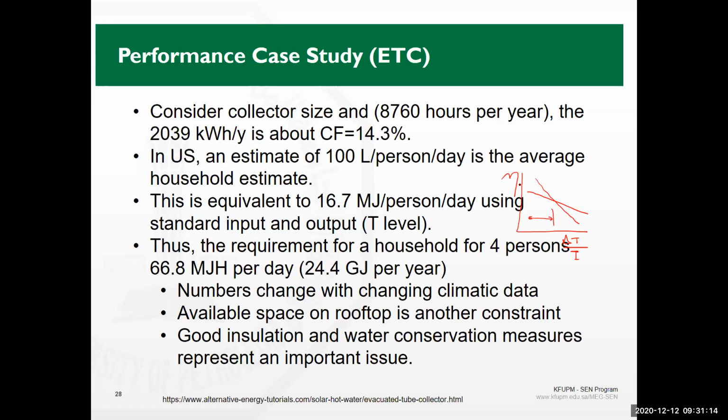So the efficiency depends on how much temperature difference you need to raise the water, and how much solar energy is falling on the collector. If the solar energy is high and the delta T is low, you may go to this area. So the efficiency of your solar collector is going to be much higher in Saudi Arabia compared to if you put it in a cold place. I hope that answers your question, and we will come back to this when we talk about efficiency. Yeah, Doctor. Okay, thank you.